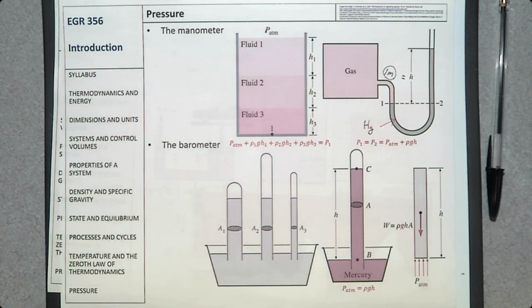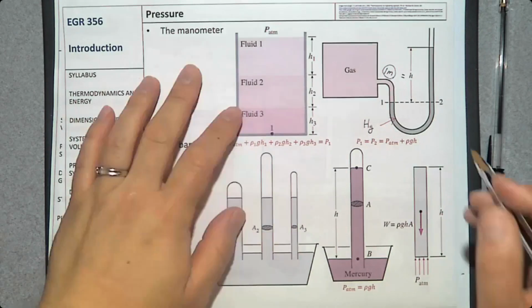The first thing you need to do is find the starting point. What is the starting point? The point whose pressure is known. What pressure is known in this diagram? Do you know any pressure at any point? Yes, we do. Which one is that? Do we know the pressure of this gas? Do we know the pressure of this mercury? It depends on the location, right? And what location? This one.